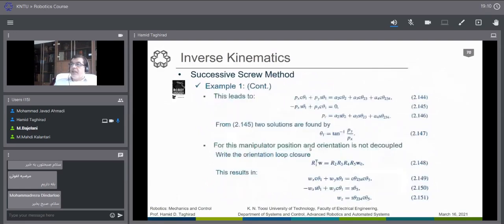And as you see in here, we have the last equation and the first equation here. So this manipulation will result into this part. Up to here, the method is different from the Denavit-Hartenberg to screw. The screw is easier in a sense that you don't need the target position and reference position point. But from here, to solve the problem is the same, as difficult as what we have in the Denavit-Hartenberg method that we used before.